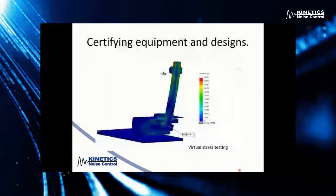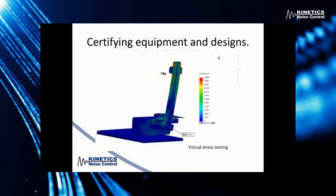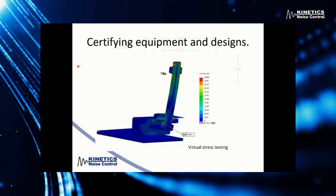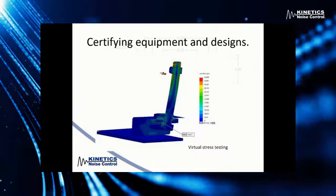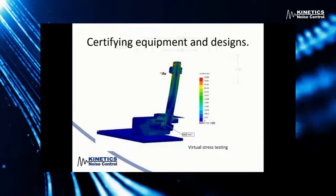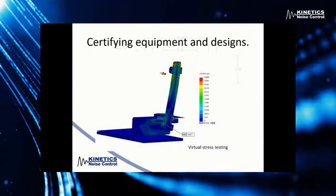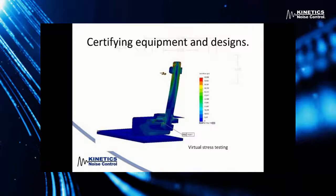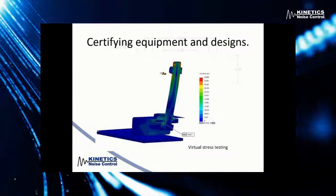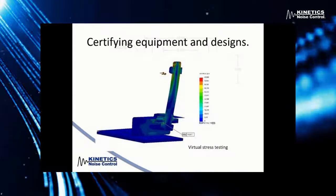And also, we do virtual stress testing. For instance, fan manufacturers have come to Kinetics, and we've taken their equipment and put it in a 3D model, and then stress tested the equipment itself, and then offered a seismic rating based on the stresses that we can do for virtual stress testing. This saves the manufacturer having to send that equipment off to have it put on a shaker table and tested for seismic forces. So that's the end of the webinar.